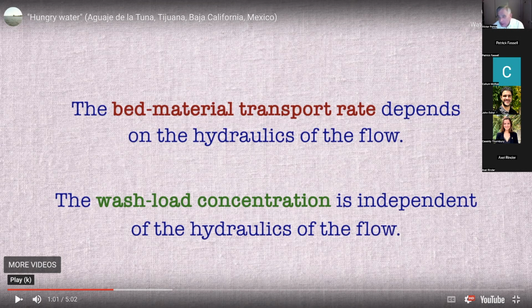So then the question at this point is, when would you get a sediment load that is more than 50,000? 50,000 sounds like a whole lot. And the answer is yes, when you have a debris flow or high concentration flows, which you every once in a while have in mountain streams. An example we have here in the San Gabriel Mountains, they have recurring debris flows every once in a while, almost every year.